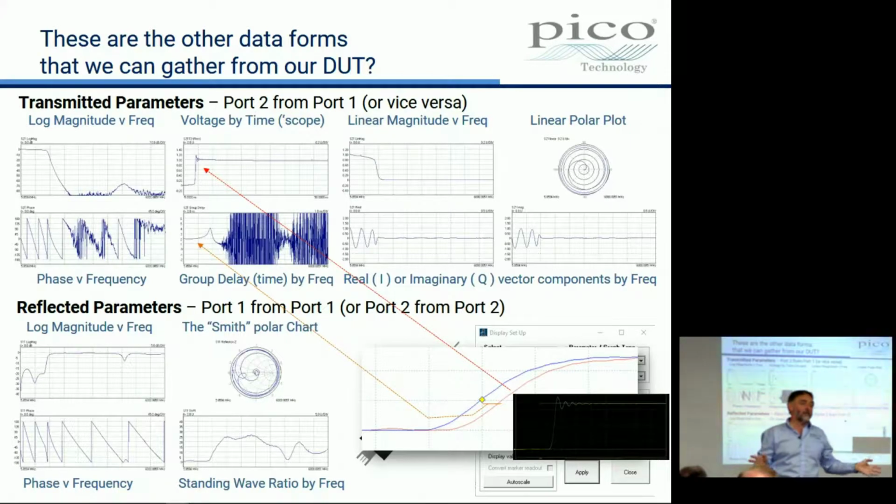And lots of you here have heard us talk a lot about, can we have S parameter analysis on the 9311, i.e. convert from the time domain? Yes, it's all possible, right? But we don't have it. Here it is. This has the transformation embedded within the vector network analyzer. Okay, so what's that? That's 8 plots. We've got 8 plots, all of the same data that are useful in different ways in analysing networks.